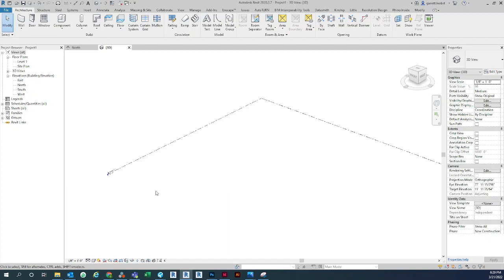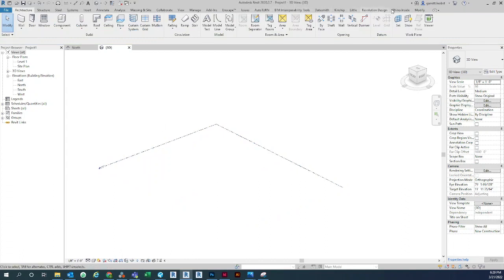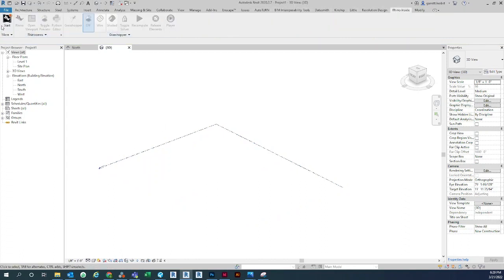We will delete that at some point once we get our level set up, but Revit does need at least one level in there. If you try and delete it, it won't let you. I'm hitting the delete button right now, and it is grayed out. So let's engage our Rhino.Inside to get that started.